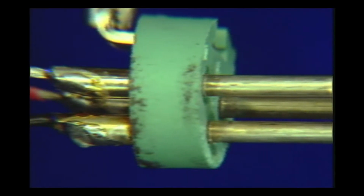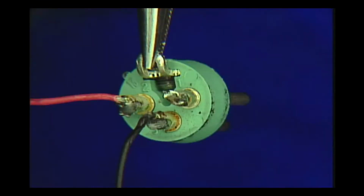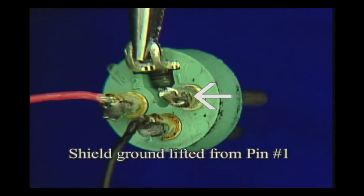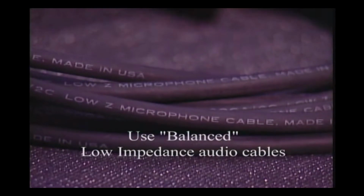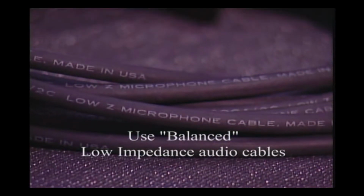Another advantage of balanced circuits is that they readily allow the shield ground to be disconnected or lifted at one end in order to avoid ground loops. The bottom line? Always use balanced low impedance lines for your microphone cables.